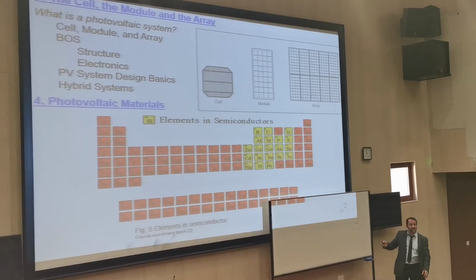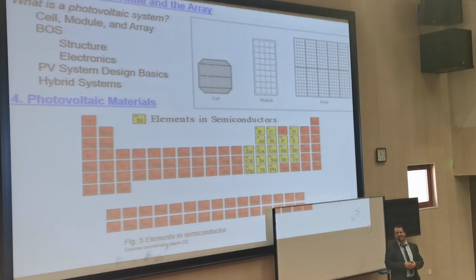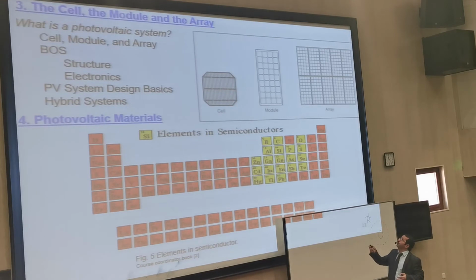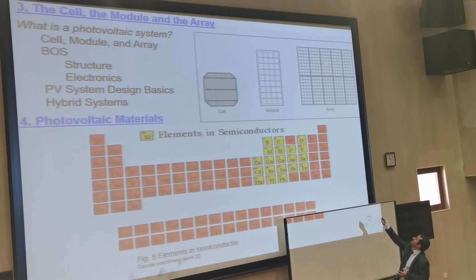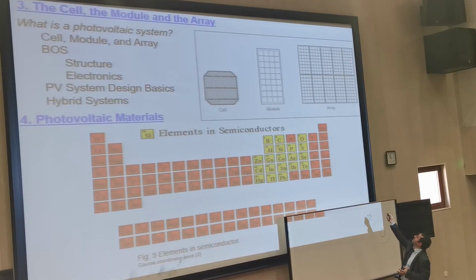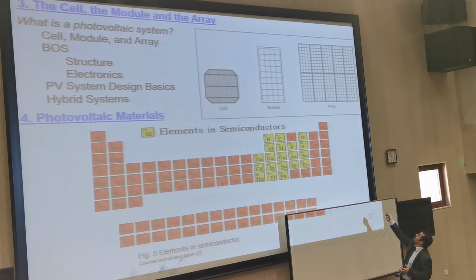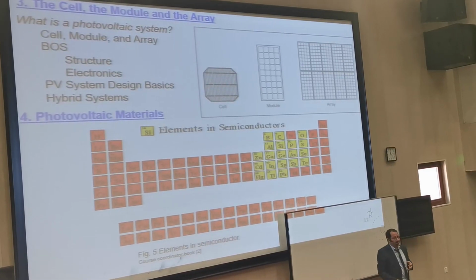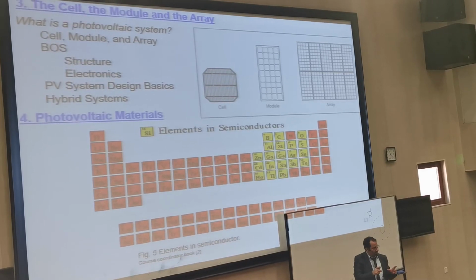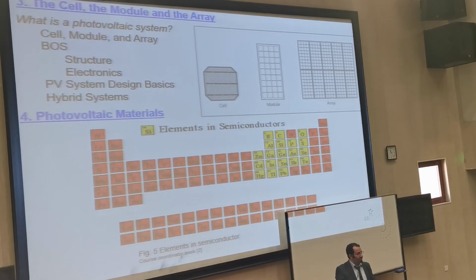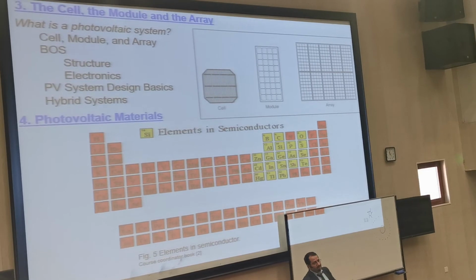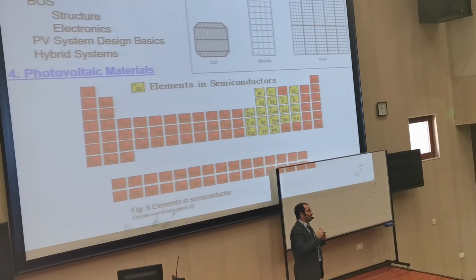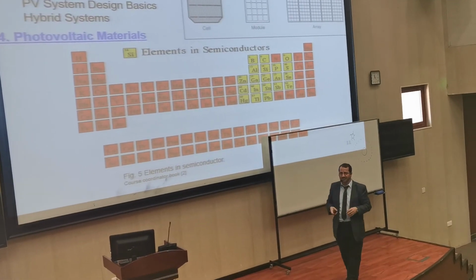We put them together in series and parallel, because we need to increase the energy produced by the panel, right? If we put these cells together in series in this way, we call this a module, or panel. If we put more than one panel, we call them an array. So the small one is the cell; put them in one frame and what do we come up with? Module. Put more than one module, and what do we come up with? Excellent, panel, then array. You got it?